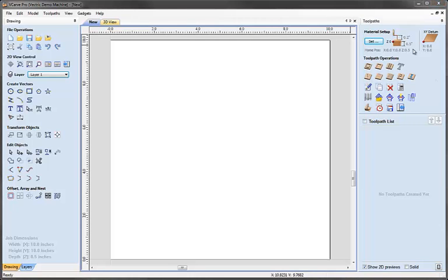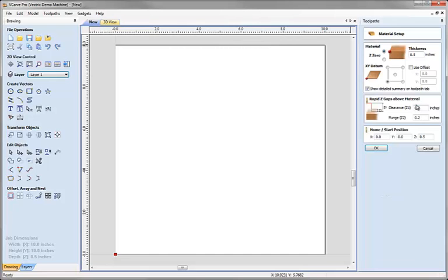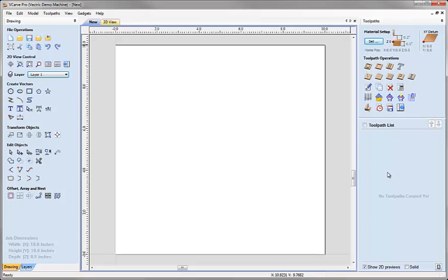At the top of the Toolpaths tab we have information about the size of our part and our datum position. This is everything we entered when we did the initial job setup, but before you calculate any toolpaths you'll always want to come into here, either double check the values visually or click on the Set button to go into the material setup form and make any edits you need to before you actually generate the data in the correct position and size that you want it for the machine.